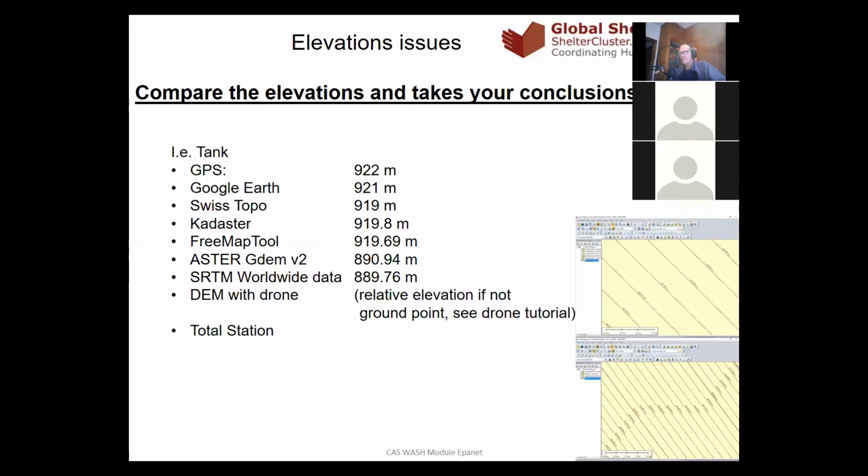And on the other hand, if you have enough energy, it means if there is enough slope, you shouldn't be too much afraid, because there is energy. The problem is only when it's rather flat, where you don't have energy. So where your reservoir, let's say, is only a few meters above the tap stand, then yes, you have to be very careful. But if you have 20 meters of pressure or 40 meters of pressure, it's no problem. And in Syria, not always you have hills. Sometimes it's flat, and in that case, it's really advised to use the total station to get the precise relative elevation.